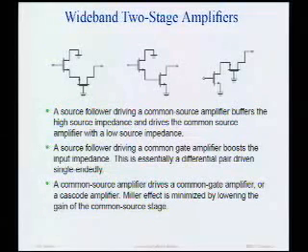You can see it doesn't have Miller effect because the first stage, by definition, doesn't have Miller effect. It has no gain. And the second stage, there's no feedback capacitance, or there's very little feedback capacitance. Usually it's mostly due to layout, but there's no intrinsic feedback capacitance in the small signal model. Okay. Any questions or comments about that?